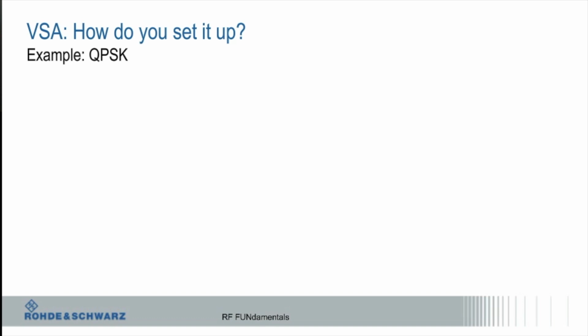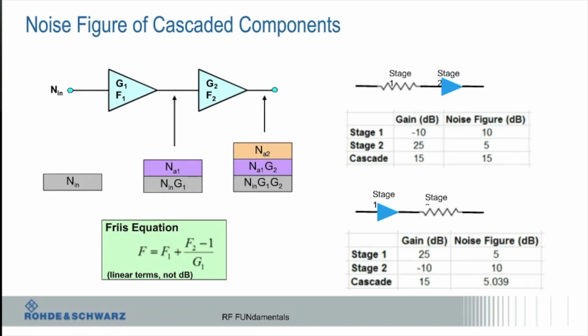So you might have a chain with mixers and all kinds of things, and you want to get the overall noise figure. If I'm trying to optimize this, then I put the best noise figure here, and I don't worry about it later on. And there are other things you care about later on that I'll talk about later. Questions? Okay, so it's just showing you an example.